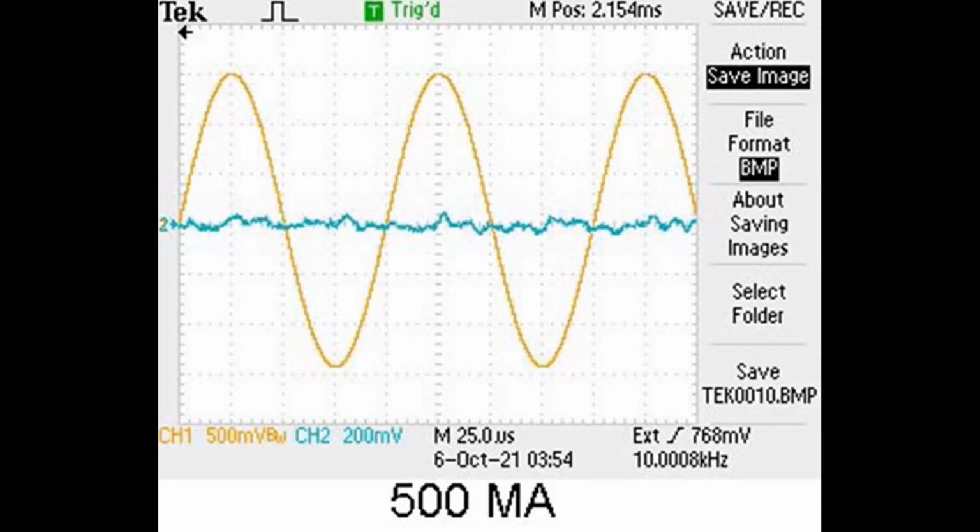I think you'll agree that was pretty cool. About the time you hit 400 milliamps, the distortion has declined about as far as it'll go in this setup, but higher current doesn't seem to create much of a problem. Just for grins, I also tried flipping the polarity of the current source at 500 mils just to see how it might be different.